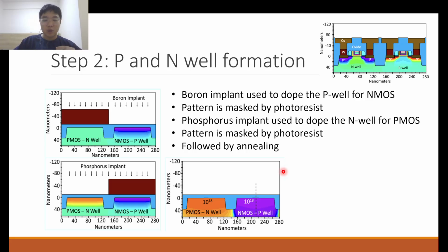At the same time, when we implant ions in the material, they may not occupy substitutional sites. And if they occupy interstitial sites, they are not electrically active. So we need to anneal it to ensure they jitter over and occupy the substitutional sites in the lattice of silicon, and that is only when the dopants are considered to be activated and electrically active.